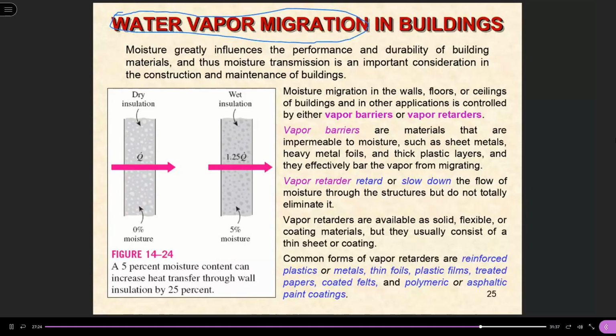Here, through a wall there could be moisture mass transfer, which we should try to minimize, especially for a building located with a basement. For the floor material, in heavy rains, the ground is very wet, right? You don't want to have water migration into your building, and for that reason understanding the water migration is very important. In fact, there's nothing different from the equation we have used.